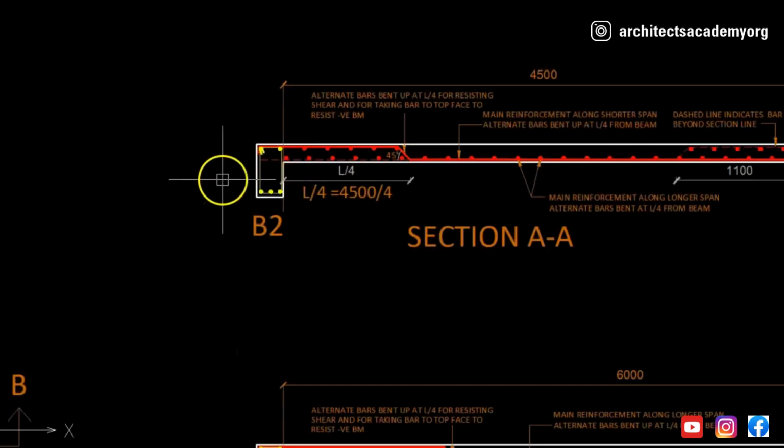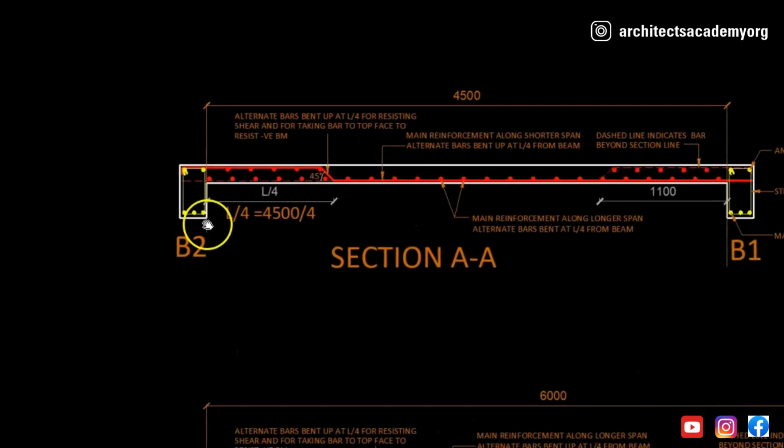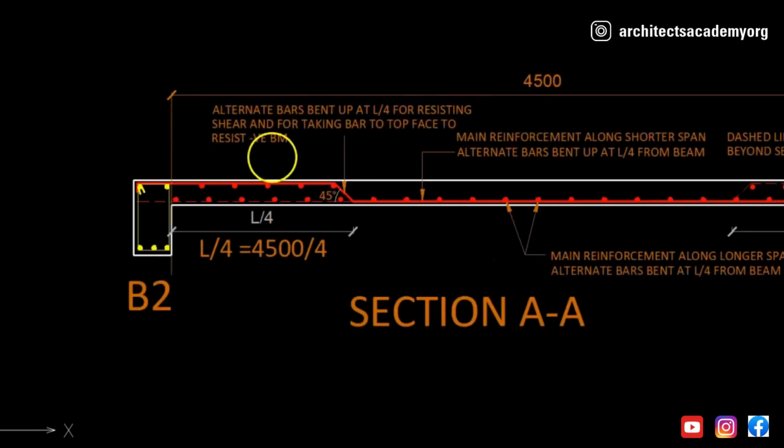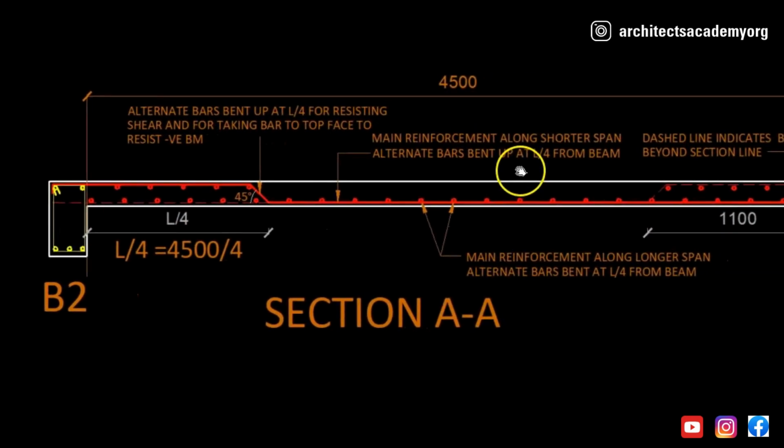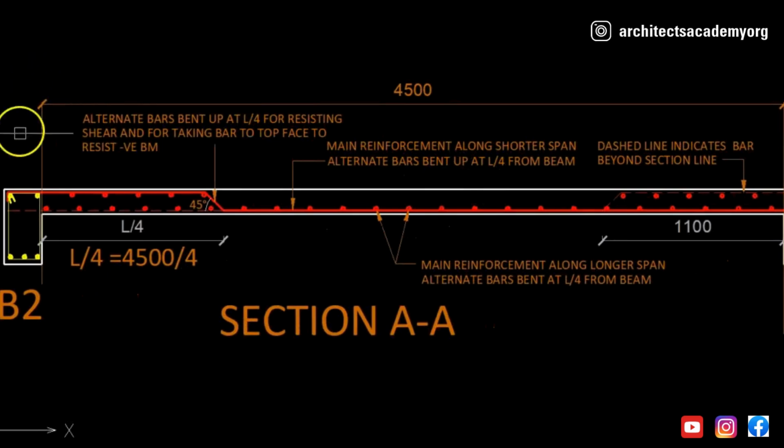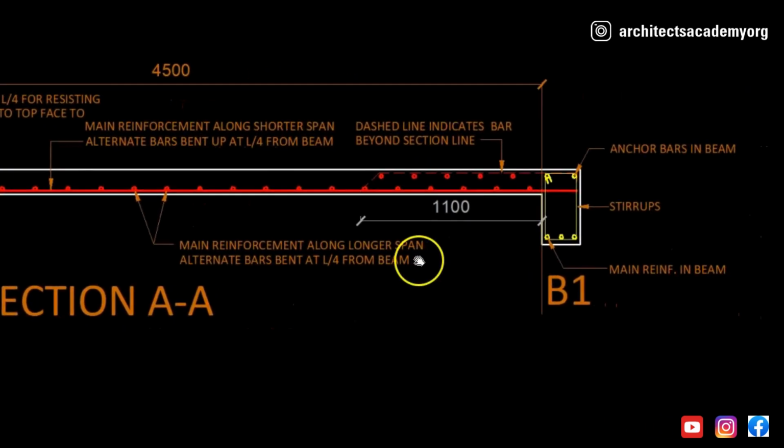Draw two sections through the slab, and also write the notes directly on the section itself, explaining some of the important concepts in the two-way slab or one-way slab. It is important that all that you know is shown in the drawing itself, in the section itself.